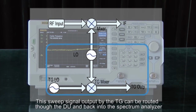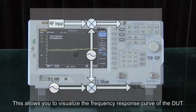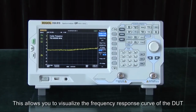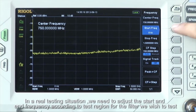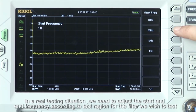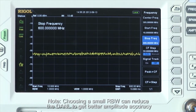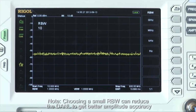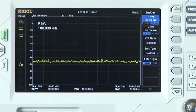The sweep signal output by the tracking generator can then be routed through the device under test and back into the spectrum analyzer. And this allows you to visualize the frequency response curve of the device under test. In a real testing situation, we need to adjust the start and end frequency according to the test region for the filter we want to test. Note, choosing a small RBW or resolution bandwidth can help reduce the DANL to get better amplitude accuracy.